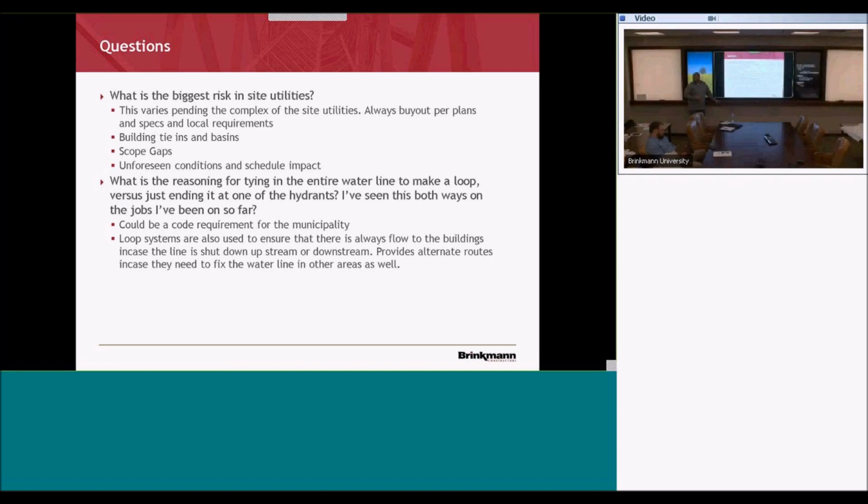Tim? And at what depth do I need a ladder in an excavation, Jacob? You don't know that? 4 feet? And at what depth do I need to worry about shoring, trenching, benching? 4 feet? 5 feet. 5 feet. But 4 feet's a better answer. With 4 feet, you can always go above and beyond.